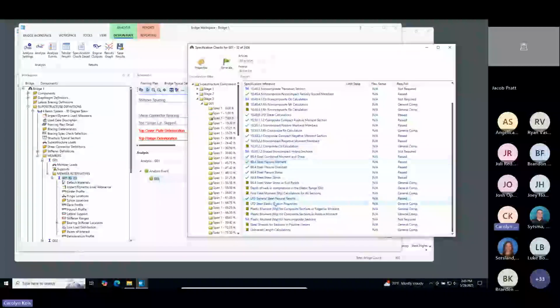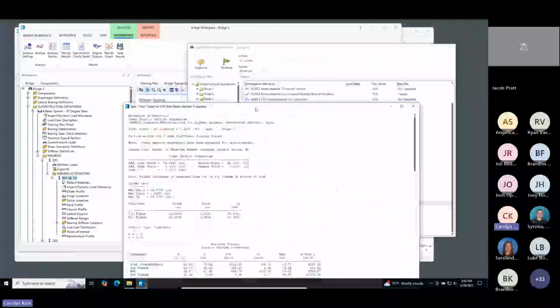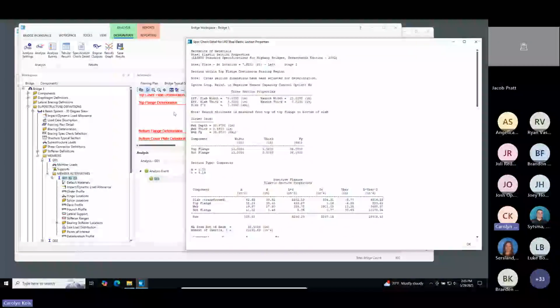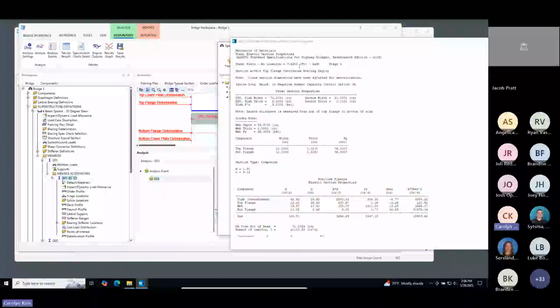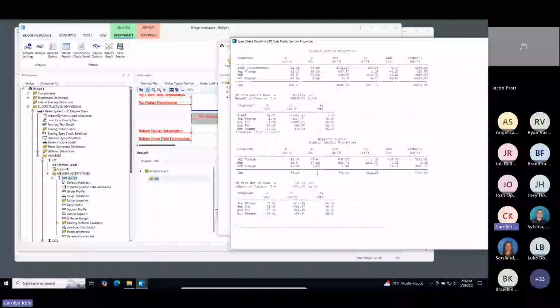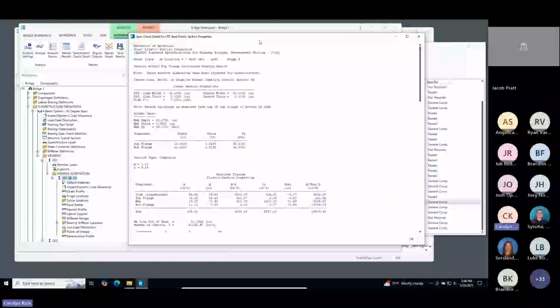And then the section properties here as well should reflect any changes you make for deterioration. So for example, this is in the end section here. Too many windows. But at this point here, it is 7.625 feet, so that's within this section where we've got some deterioration entered. And we can see here that the bottom flange reflects that. So this can be a good place to look to confirm and assess how that model is behaving based on the changes.